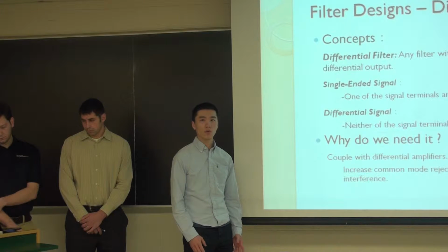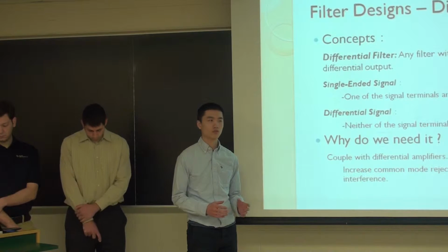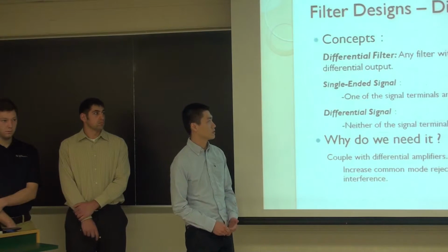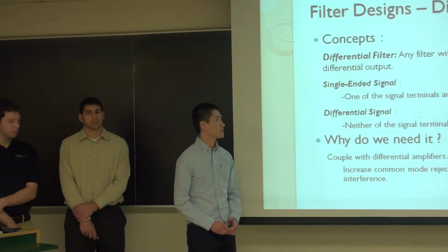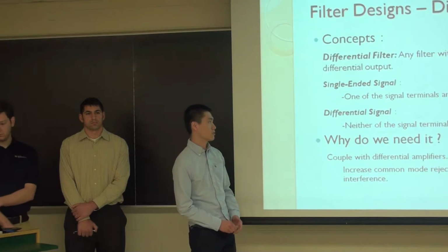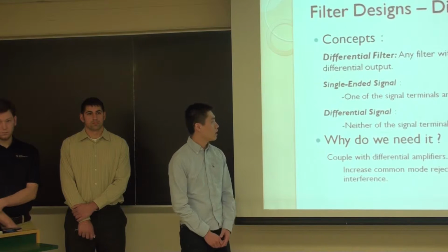As we know, when we measure a voltage signal, we need to give a reference point. Usually it's ground. So if one of the signal terminals is grounded, it's called a single-ended signal. And if neither of the signal terminals is grounded, it's a differential signal.